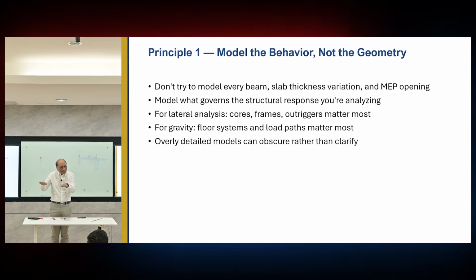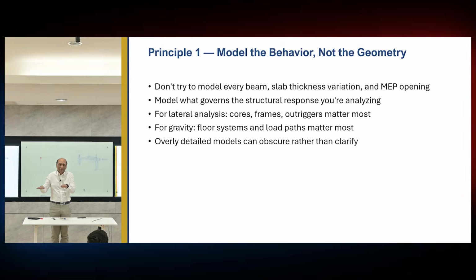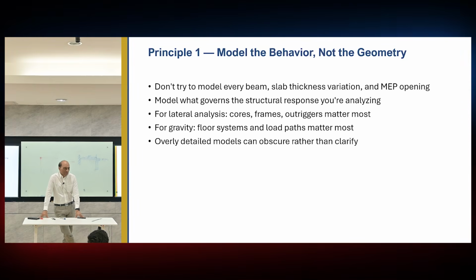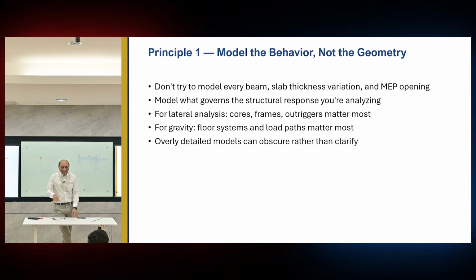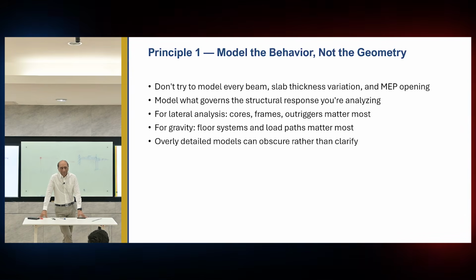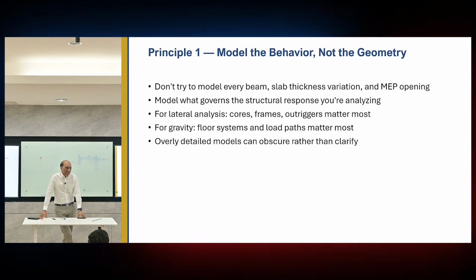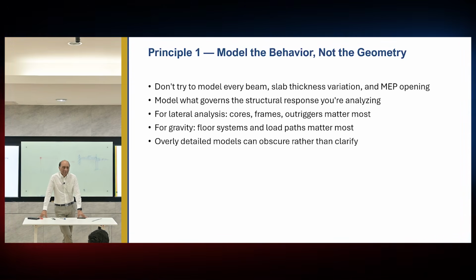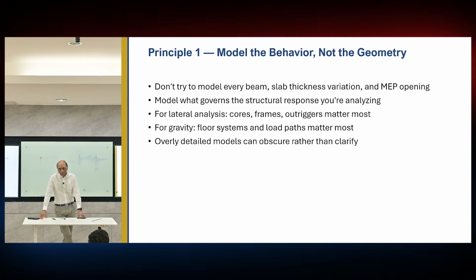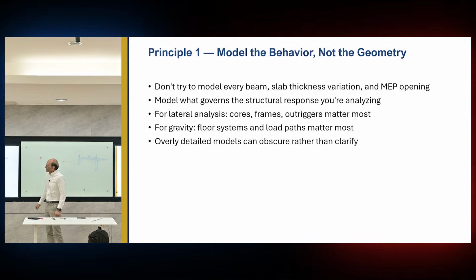And if you now just change your model from a flat floor to an inclined floor, you will be in huge trouble, because ETABS doesn't have a sloping floor. So it will create so many stories and ramps, and it will just complicate your problem for nothing. You could have easily ignored that small angle and made it flat. So things like this can mess up your model. So be careful with that.